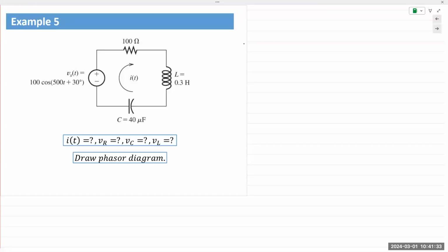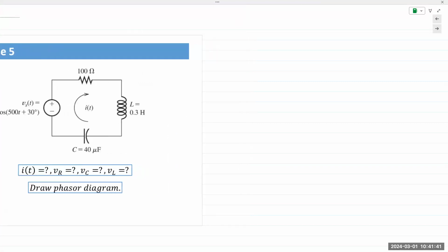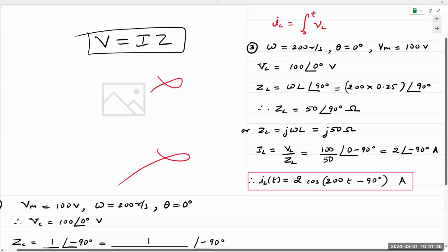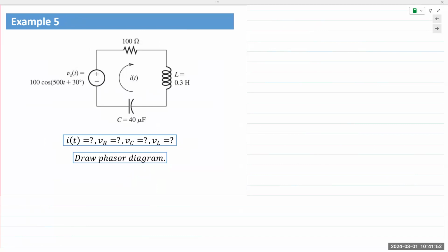We see a circuit which has 3 components, R, L, and C. All 3 components are on there. So the first thing I would tell students to do here is to draw out the equivalent impedance diagram. When you see a circuit like this for AC analysis, the first thing is to draw out the equivalent impedance diagram.